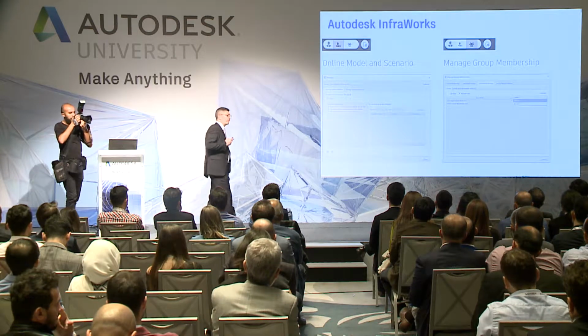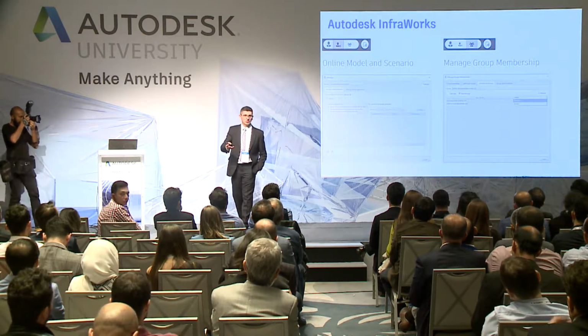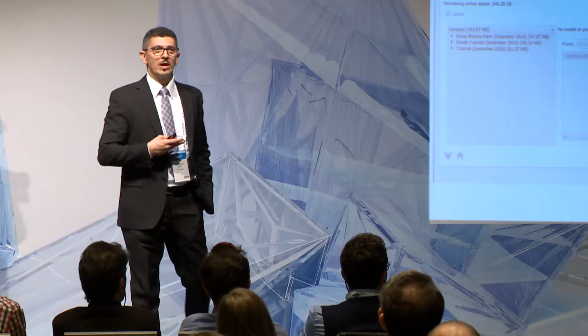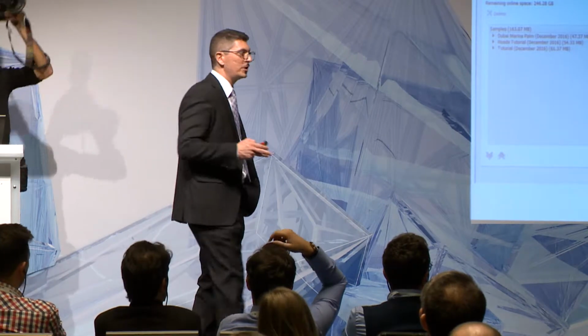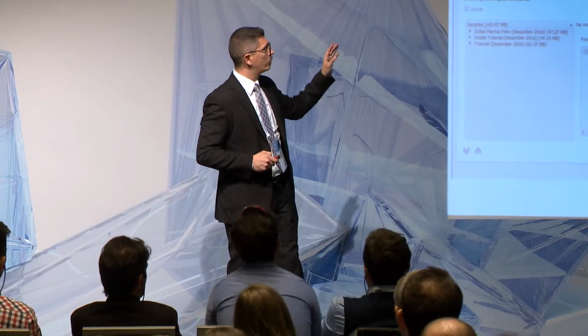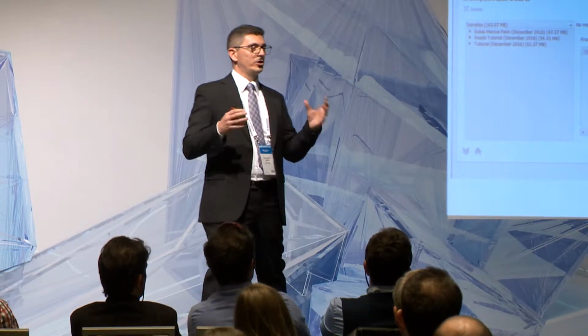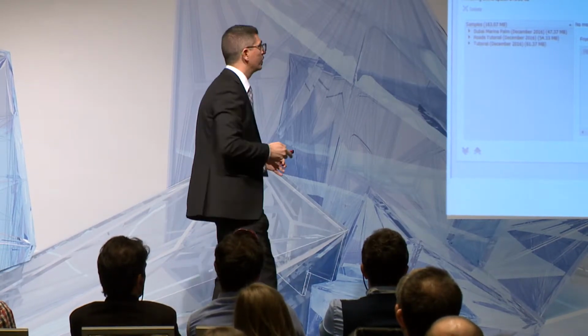One of the important things about BIM is sharing data, sharing information. And with InfraWorks, we have the possibility to share also our model. We can take the model that we already see and share it without anything else. It's possible to do this by creating a scenario. A scenario is like a portion of your model, and to publish on the cloud.